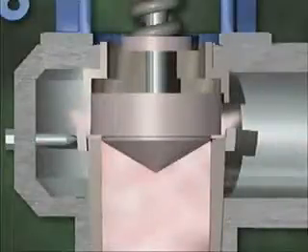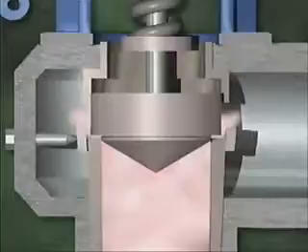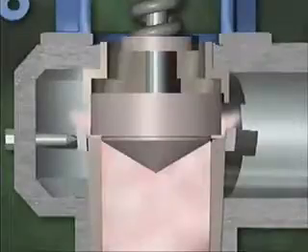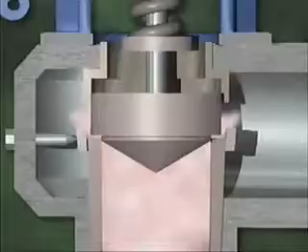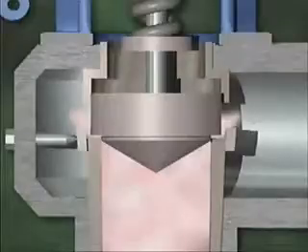The spring tension in a safety valve is preset, and it must be correct for the valve to operate properly. When the system pressure drops to the point where the valve popped open, 1,000 psi in this case, the valve doesn't close, because the lip of the disc is still exposed to the pressure and velocity of the escaping fluid.